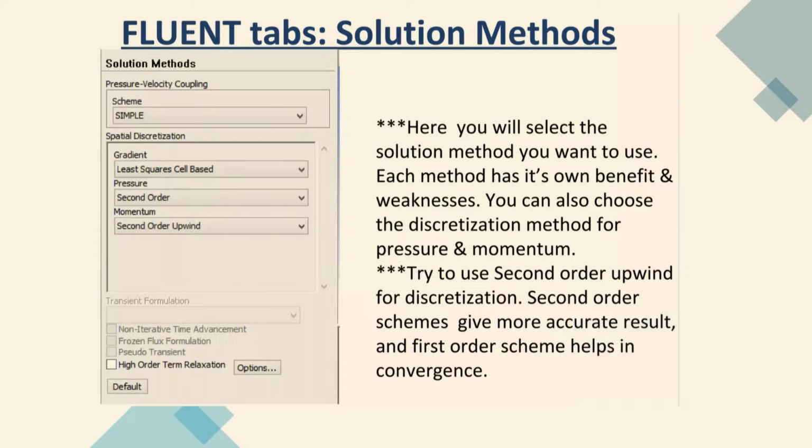And solution method. Okay. Yeah, sorry, we forgot the solution method. Here we mentioned that for solution method we have the pressure velocity coupling. Okay. So, you see the pressure velocity coupling in the momentum equation, you see the pressure on the right side, minus 1 by rho del P del x. That is called the pressure gradient. For that one there are schemes, we use the SIMPLE scheme. There are some others, it's called PISO or something. There are a lot of schemes there.